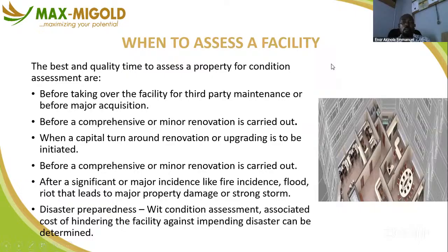So when is the best period to assess a facility? When you want to conduct the facility condition assessment, when is the best time to do it? One, the best and quality time to assess a property for condition assessment is before taking over the facility for third-party maintenance or before a major acquisition.